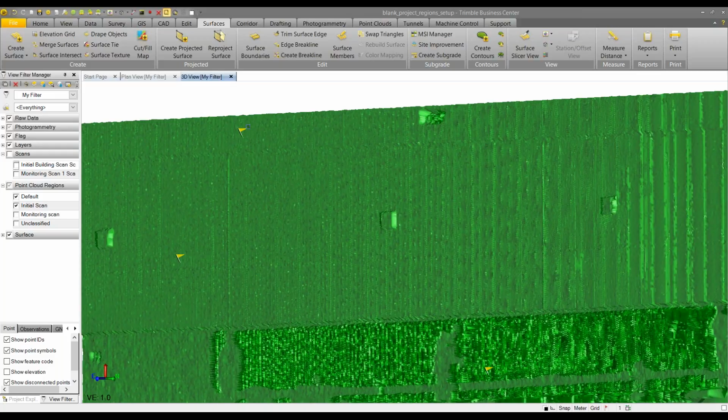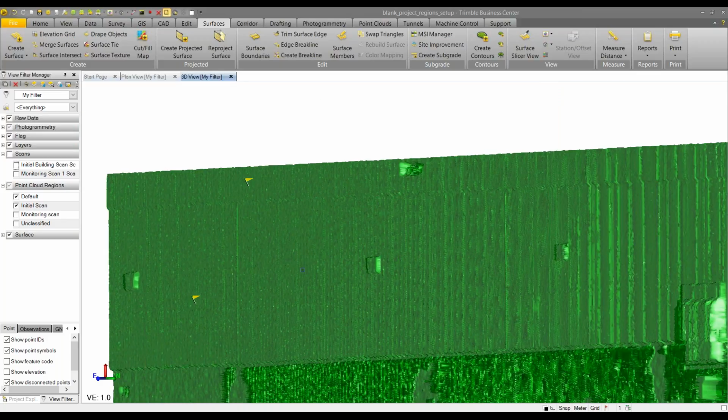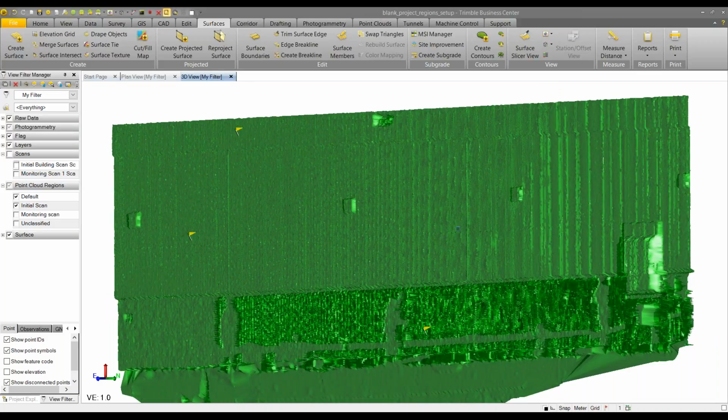Typically those flags represent points that are right on top of each other, and these can still occur even if you tried your best to make that plane definition work with your vertical surface. Sometimes there are still a few points in there from triangulation error or error from your scanning instrument that can create flags. Typically they're not a big deal unless you notice something strange during your analysis, but we haven't had any problems with them.